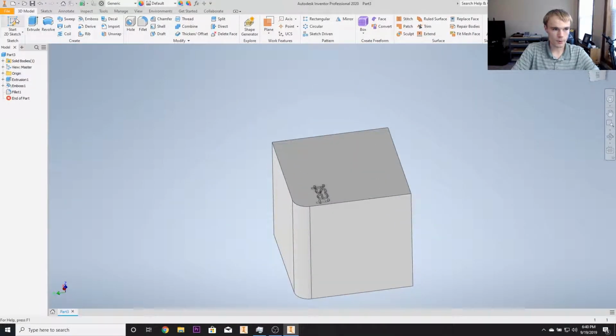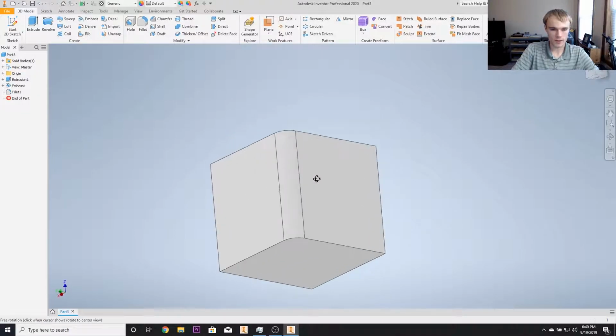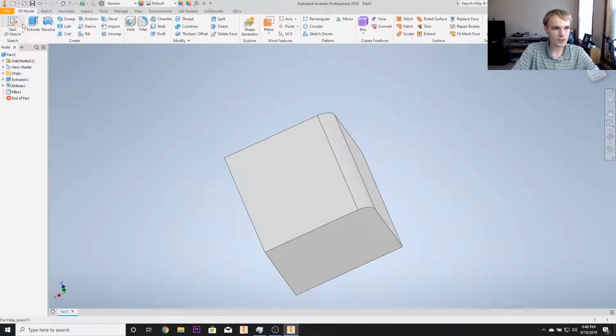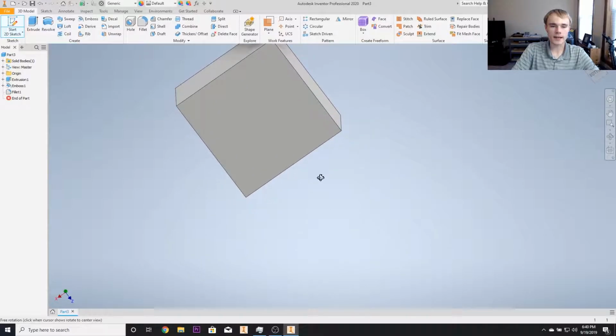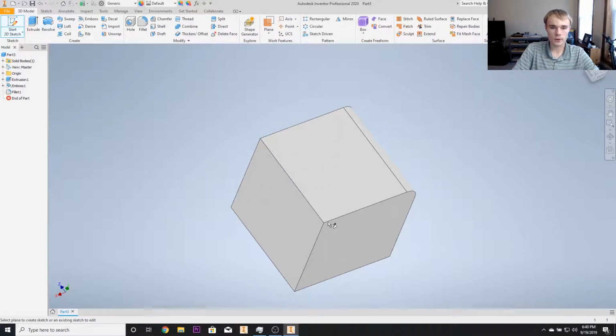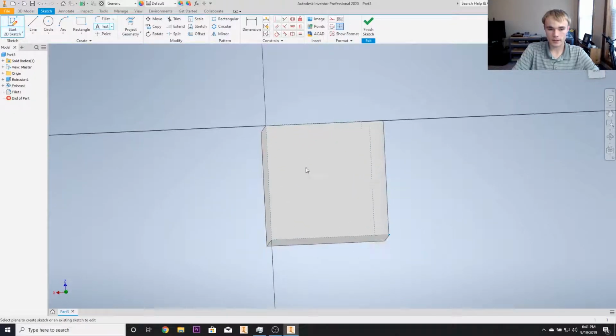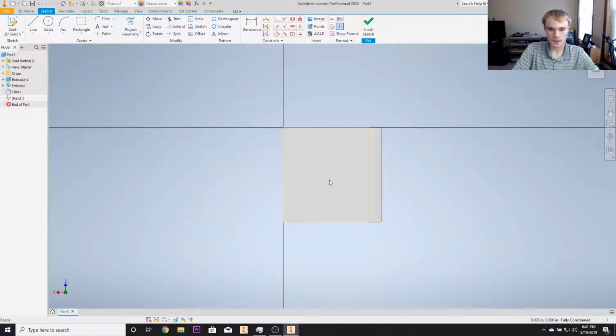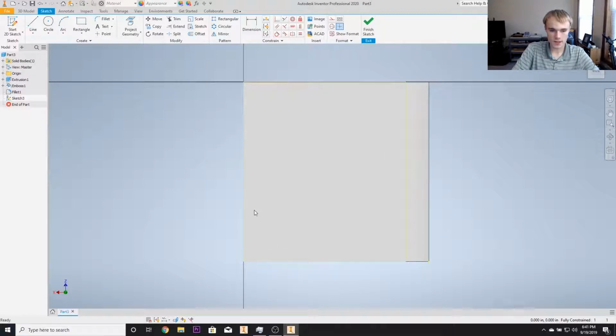object. So if we now say we want to remove something from this object, we can go over here, start 2D sketch, and then we can select any face of this cube. Now say I want to create a circle going right through the center of this top face. I can select, okay, click start sketch like I already did, then you click here. Alright, it creates a sketch. So now we've got the sketch and we've got these edges selected around here, and those are just a reference point for the sketch. This is how big the sketch actually is.